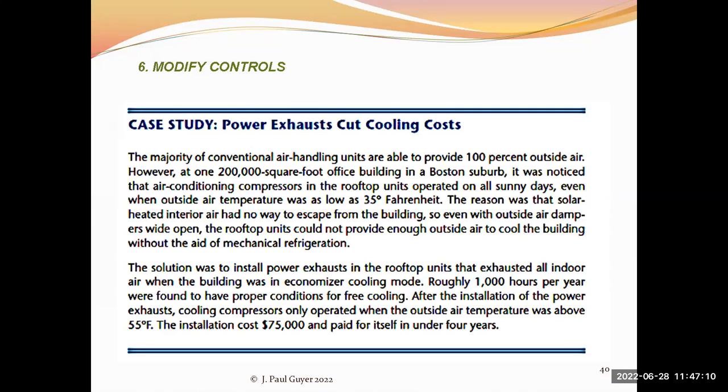And in this example, with a powered exhaust, the cooling compressors only operated when the temperature was above 55 Fahrenheit. And the installation of the power exhaust system cost $75,000. And it paid for itself. It had a payback period of under 4 years. So that was a good investment.